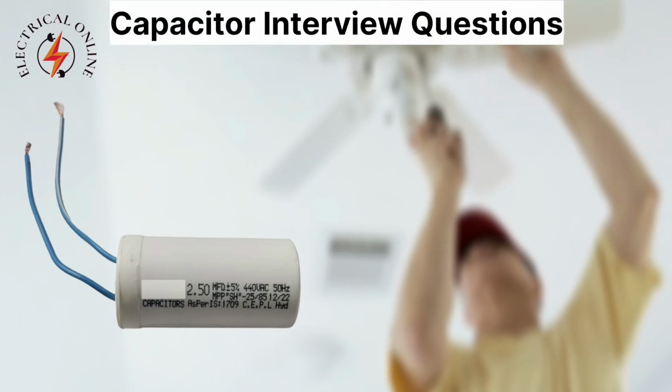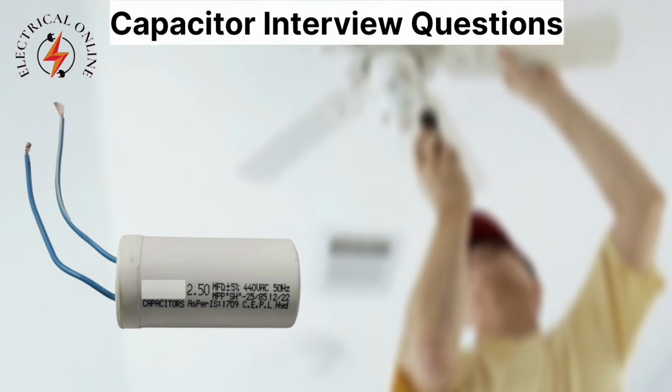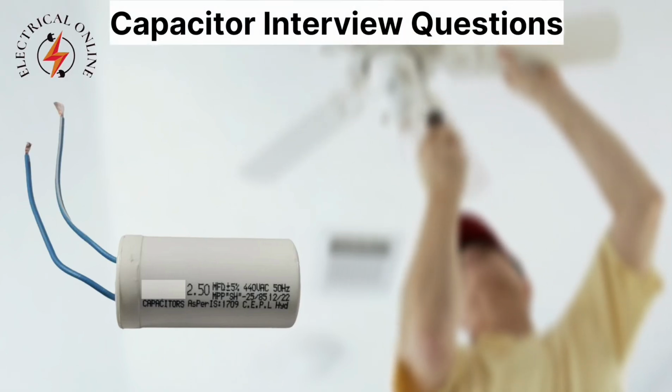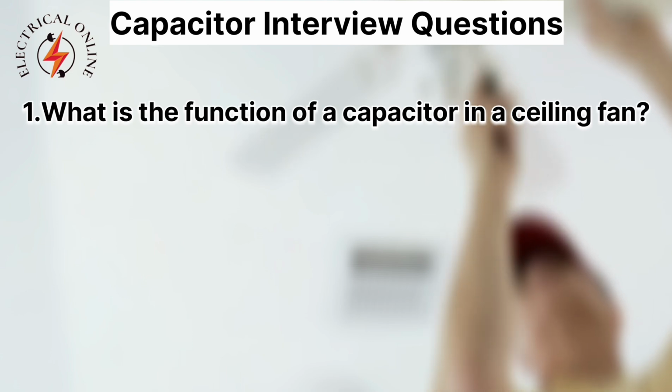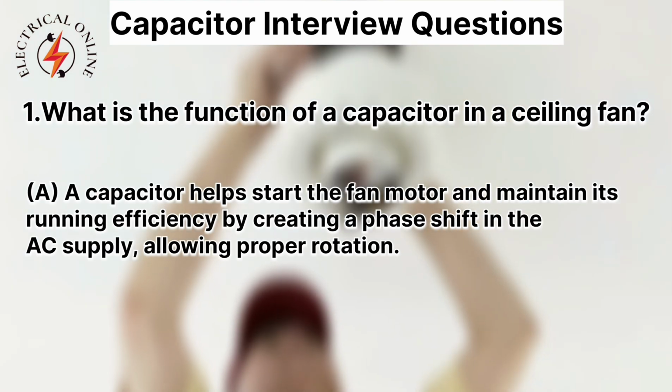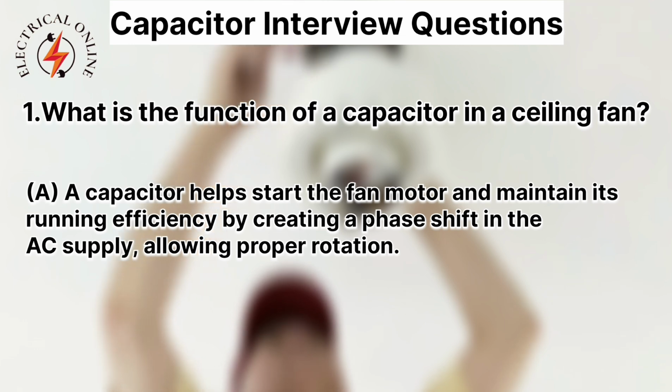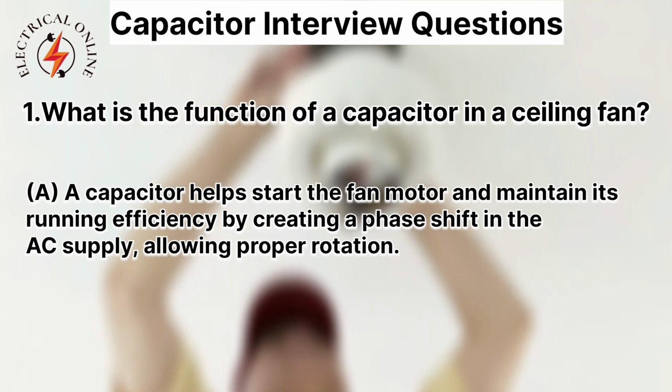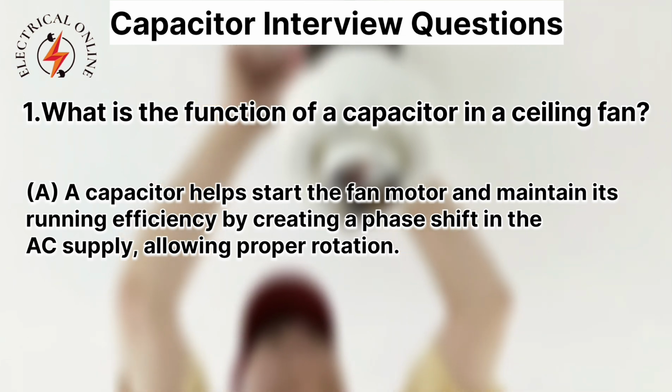Here are some important questions asked in interviews regarding ceiling fan capacitors. 1. What is the function of a capacitor in a ceiling fan? A capacitor helps start the fan motor and maintain its running efficiency by creating a phase shift in the AC supply, allowing proper rotation.